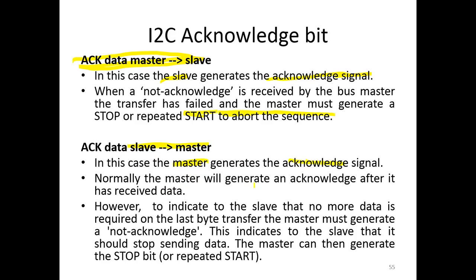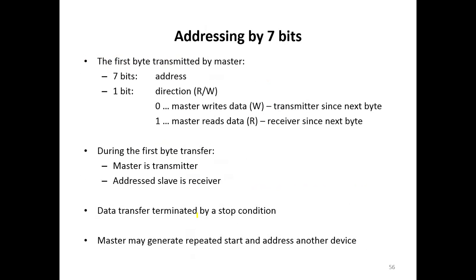Normally the master will generate the acknowledge after it has received the data. If the master is done with the transmission, it can generate the stop condition.